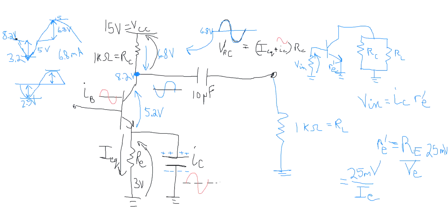So we also are going to look at the KCL of this circuit and say that the current flowing through the collector has to equal that current flowing through RE. We're going to assume that the base current is negligible. So now we can make a very important simplification. We're going to write the output voltage. Okay, hope you have those notes. Let's erase that. The output voltage in terms of RC and RL. You could do this yourself. So V out.